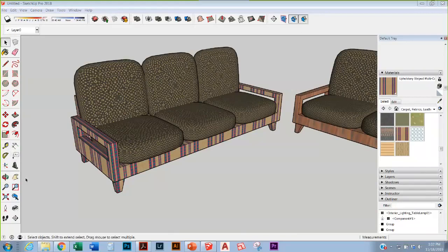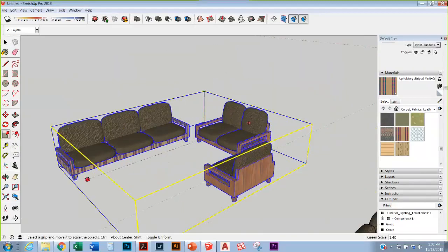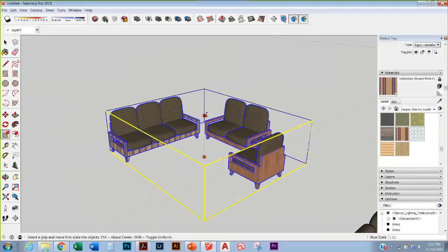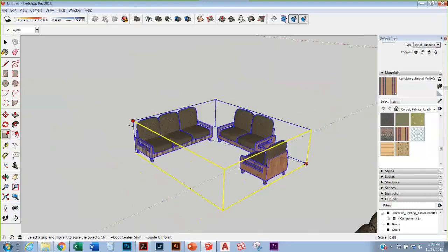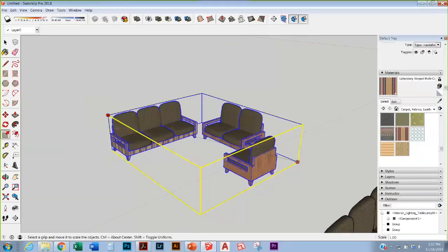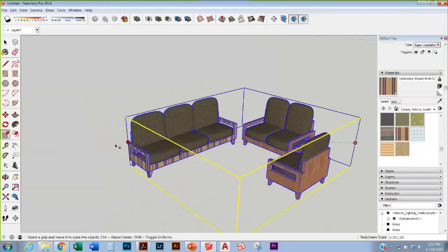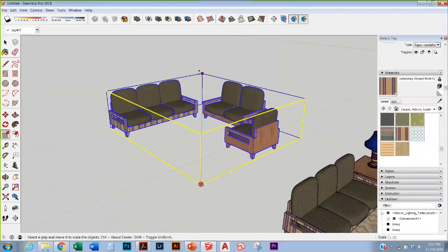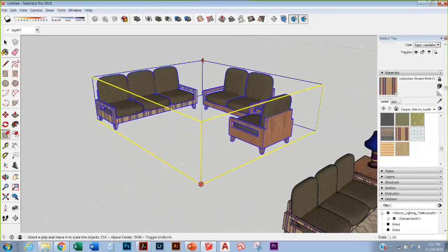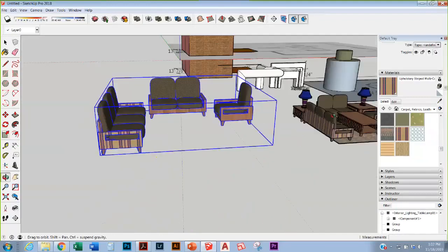The last tools here in this section, again, this was the scale. Y'all saw me show that. We can scale things in all the different dimensions, whether it's top, bottom, but if you hold a corner, it actually scales it all together and keeps the height, width, and depth all proportional. But again, there's all kinds of different things you can do there. You can also type in a number for your scale. I can scale it here and look at my bottom right hand corner. You see the scale 1.2, 1.3, 1.5. I can just type in 1.65 if you know the dimension, and just boom, you make it into jumbo size.